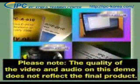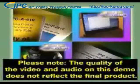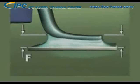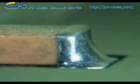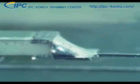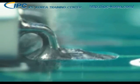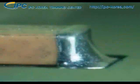Now that you've been introduced to the concept of acceptance requirements, product classes, and soldering terminology, let's examine the dimensional criteria for Class 3 surface mount solder joints. We'll start by reviewing the target condition, or the ideal surface mount solder joint for rectangular chip components, J-lead components, and gull wing components. Notice how the solder feathers smoothly onto the land and up onto the lead. The solder fillet is curved inward or concave.